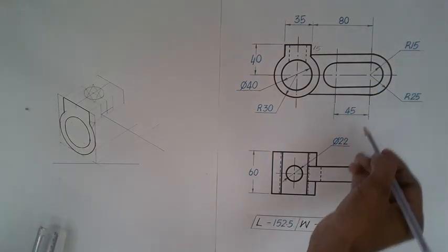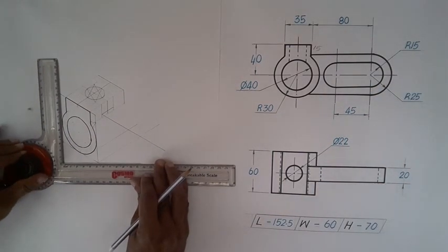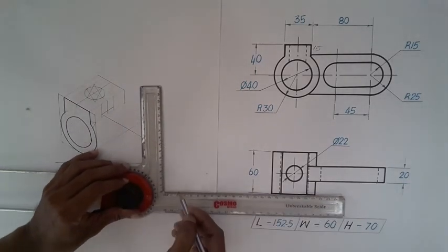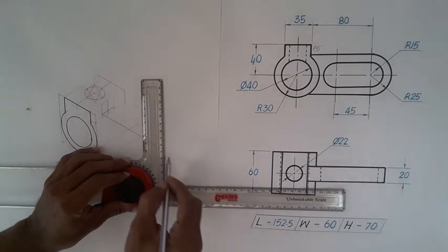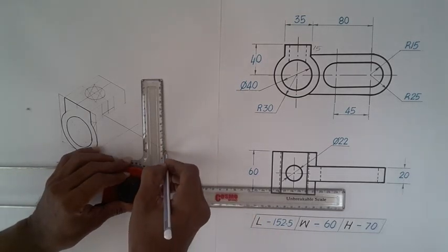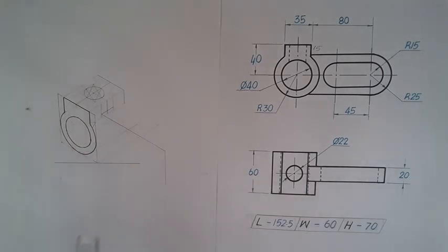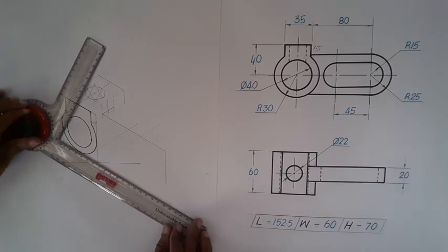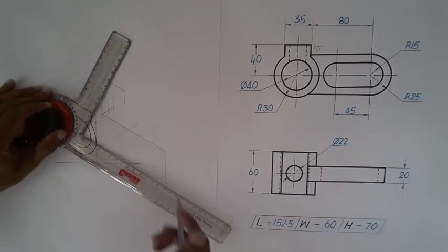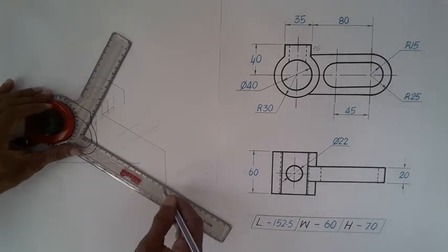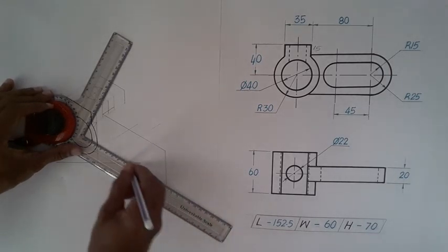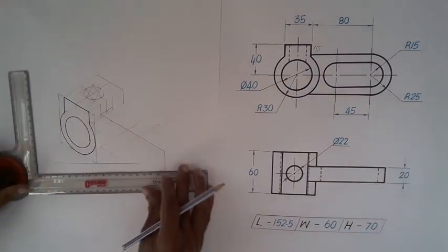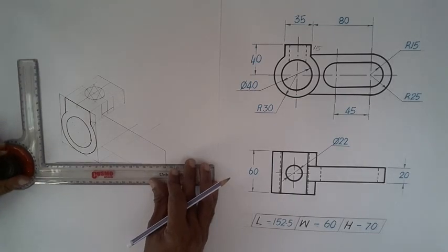And the total depth is 50 mm. Now I am marking, I am drawing a line of 50 mm length. Again, we can try to complete this rectangle by drawing a line in the isometric y direction. And the thickness is 20 mm, so we can complete